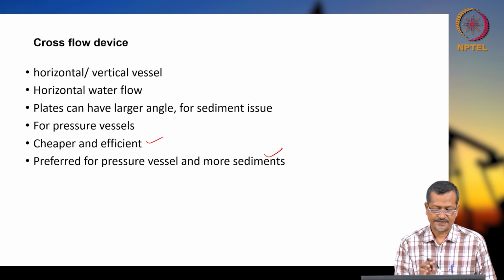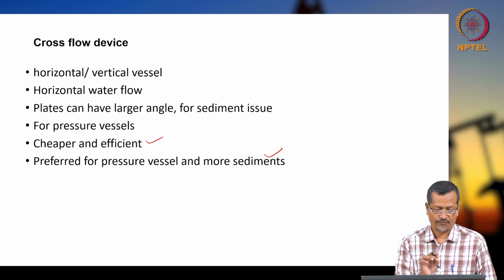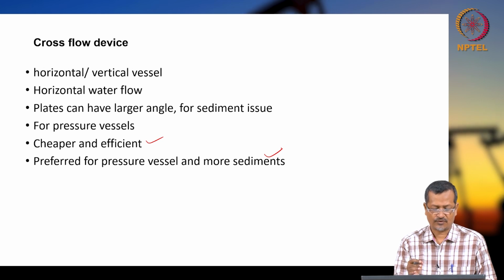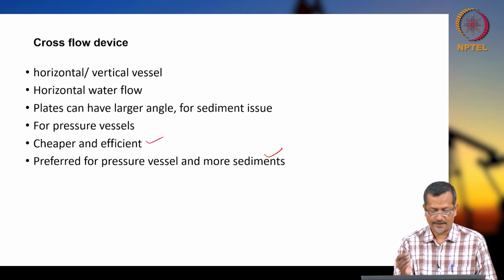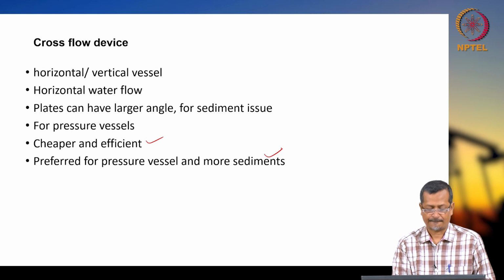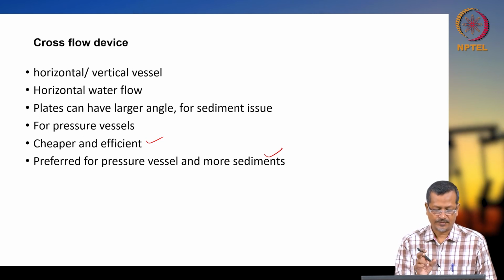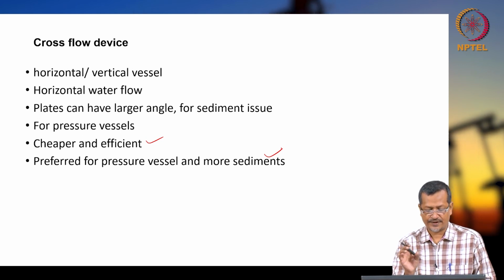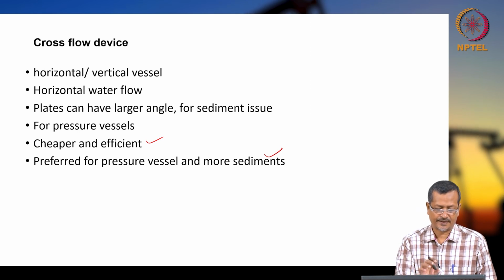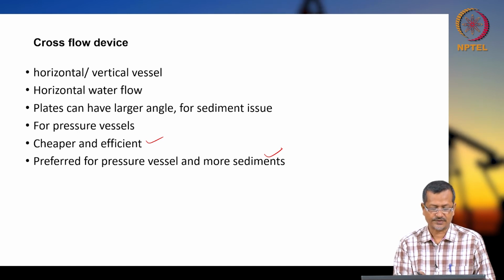Horizontal vessels require less internal baffling, as the ends of nearly each plate contact the oil-water interface directly. However, the pack is long and narrow, and therefore it requires an elaborate spreader and collector device to force water to travel across the plate pack and plug.